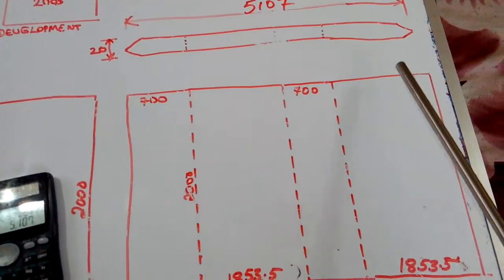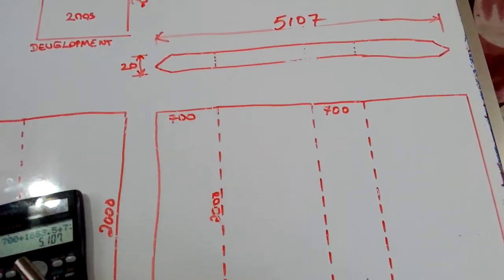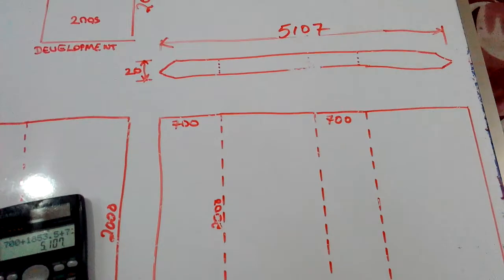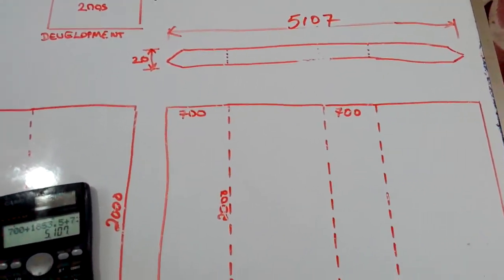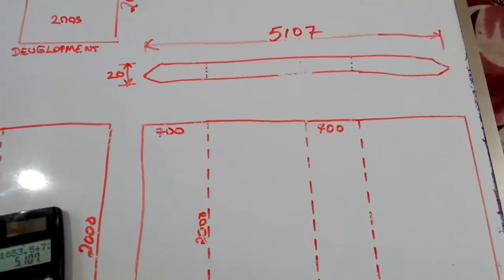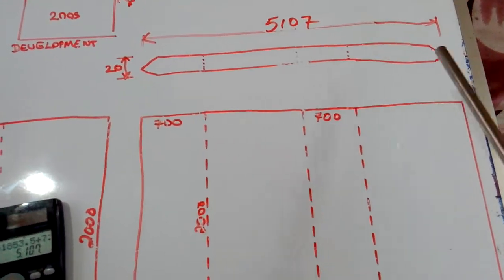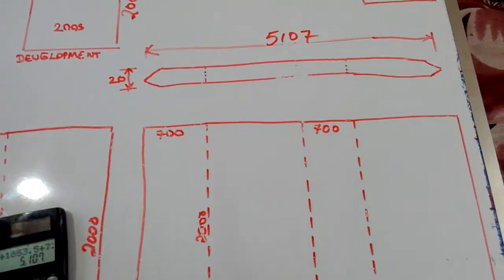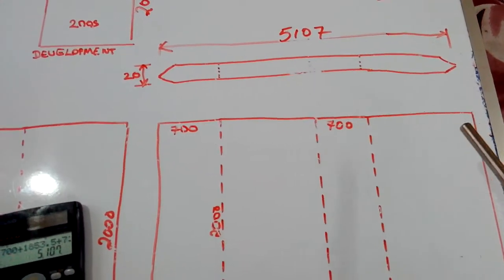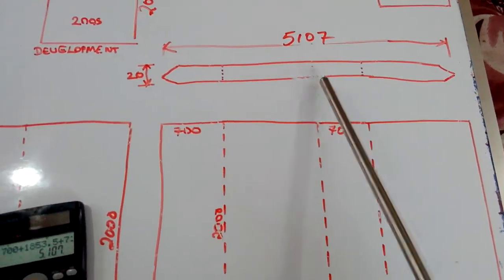Another thing, after making this one, this job will have shrinkage. It will come down because of welding. This measurement will decrease to a smaller amount. So we have to take some more length, some 1, 2, 3, whatever shrinkage will happen, that will have to be added. Those can be described in coming episodes.